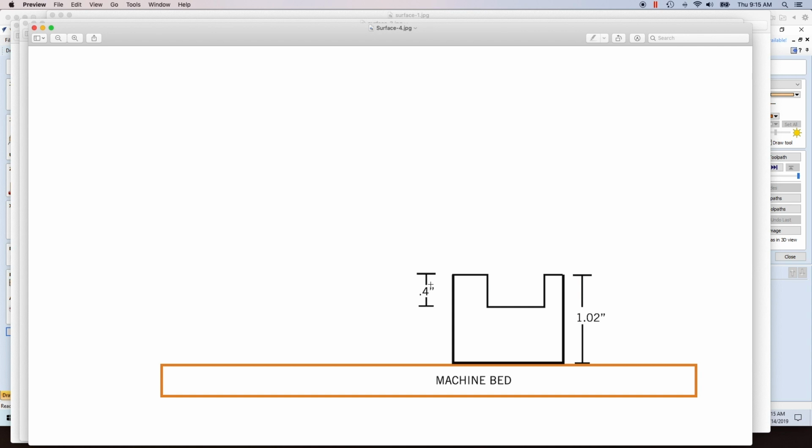In a case of plywood, though, it's not common that you would normally surface the entire sheet of plywood with a fly cutter in order to make sure that you get accurate Z depths. You know that there's going to be some tolerance, and that's just kind of fit into it. So if you had a part that had to be glued into this pocket, and you're off 20 thousandths, it's really not going to make too much of a difference. You're probably not even going to know that because the glue is going to fill up some of that space.